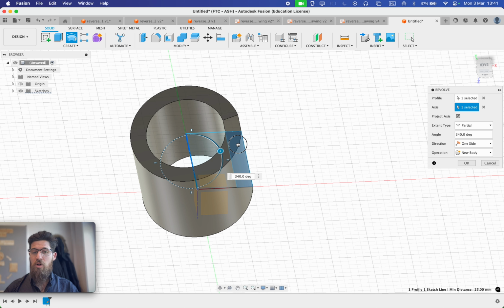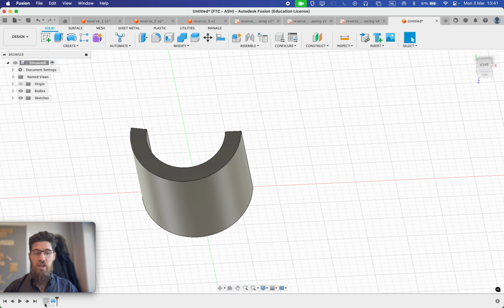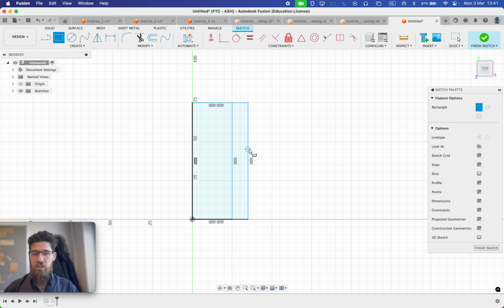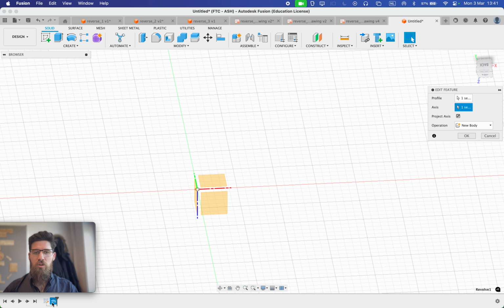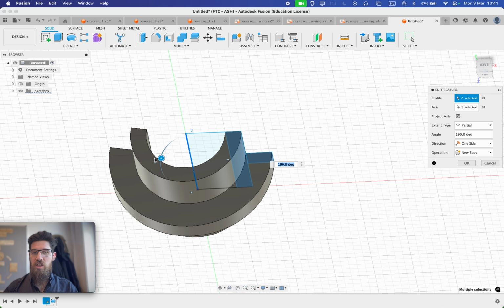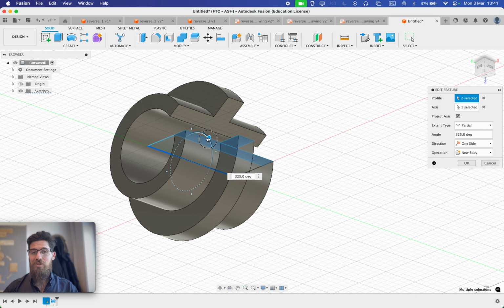You can decide to wrap it all the way around for a full 360 degrees. You can do just 3/4. You do whatever. You can have a lot of complex shapes that you can be making inside of this. Like if I were to come back and edit my sketch here, let's add in another rectangle out like so that we can make a key shape. We'll edit our revolve. We'll add in this key shape. And now as we revolve around, we are revolving around a nice letter T.